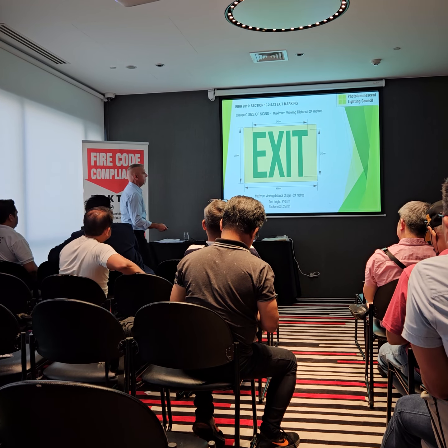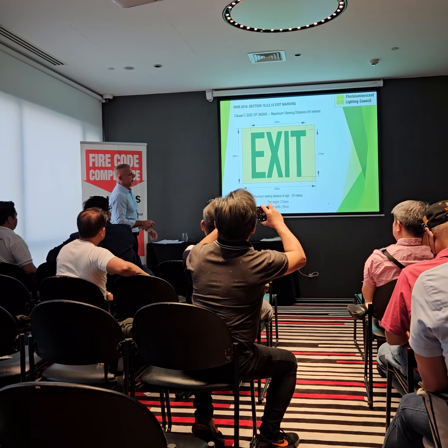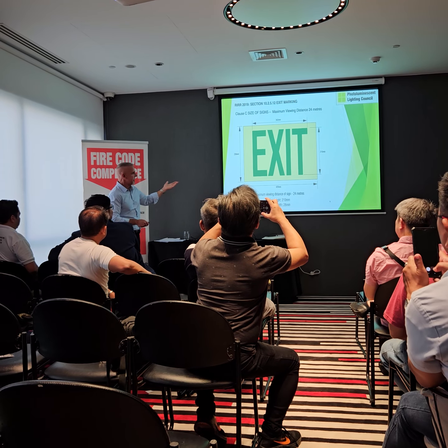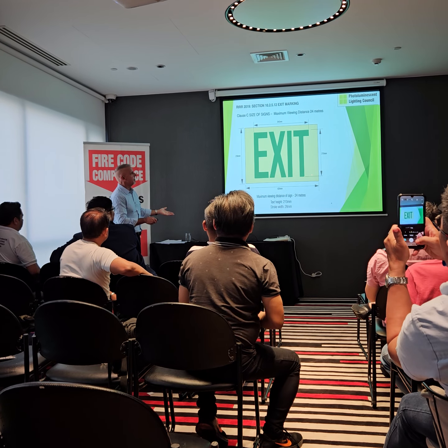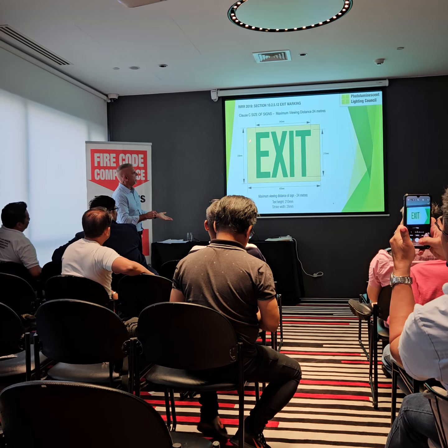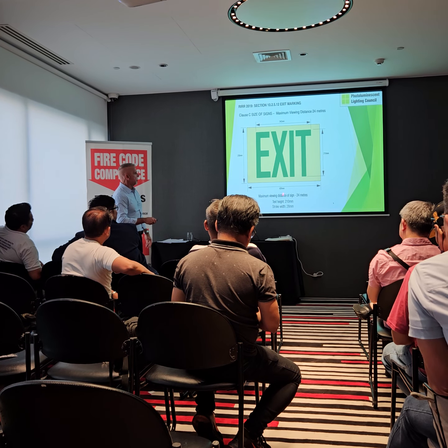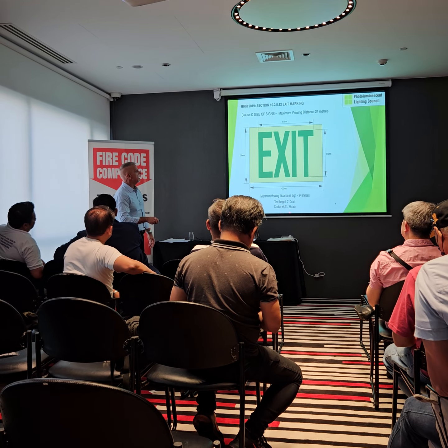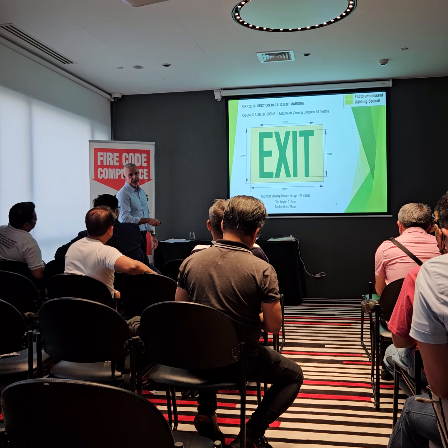And then we've gone to the size of sign from some of those other standards that's suitable for 24 metres. All we've done is scale up the text, so it's now 210 millimetres high, and the stroke width has gone up a bit to 28, but it gives it a viewing distance of 24 metres.